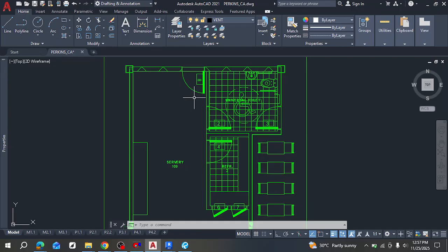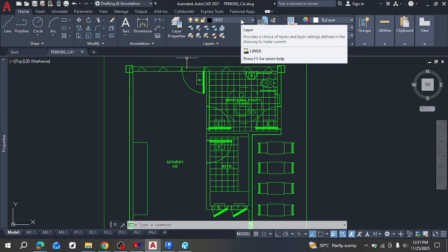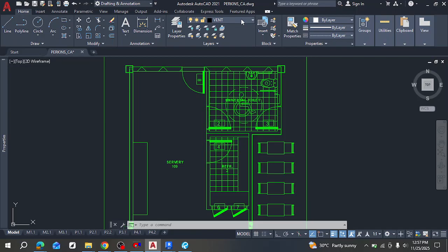And that also means that if you are working with 400 CFM per ton, the 3 ton unit is going to give us approximately 1200 CFM. So now I'm going to redesign this piece so that it is able to have that amount of air, that volume of air.